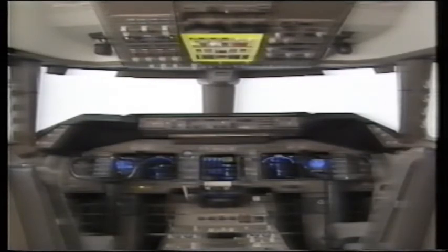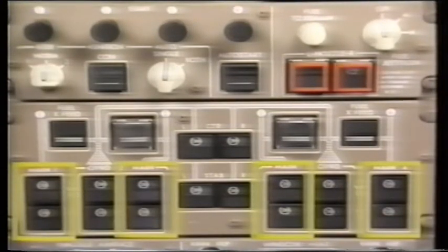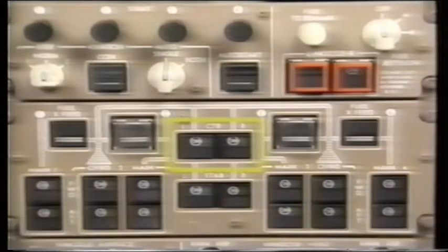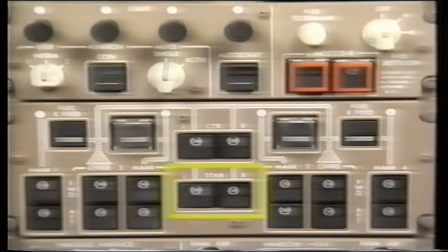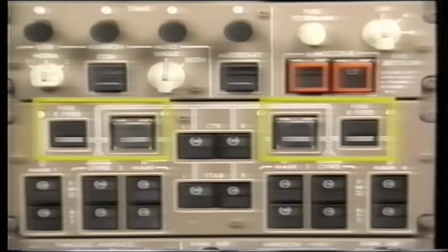Flight deck control of the fuel feed components is through the fuel management panel on the P5 overhead. It has 8 switches to control the fuel boost pumps, 2 switches for the center wing tank override jettison pumps, 2 switches for the HST transfer pumps, 4 switches for the inboard main tank override jettison pumps, and 4 switches for the cross-feed valves.